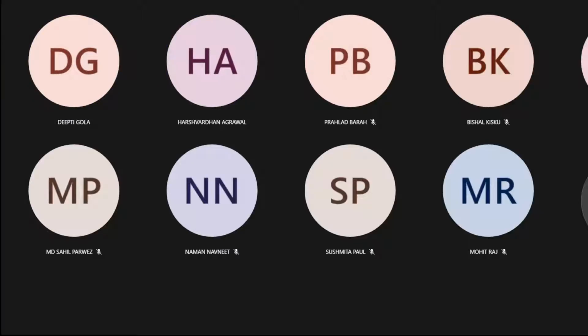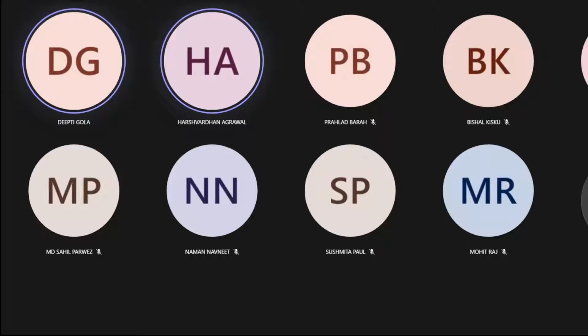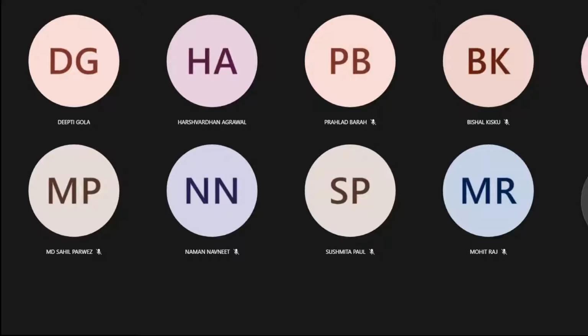Yes, ma'am. And change the values of the capacitors to 100 nanofarad and the values of R1 and R2 to 80 kilo ohms. Blinking, right? That means the current is flowing alternately, right?